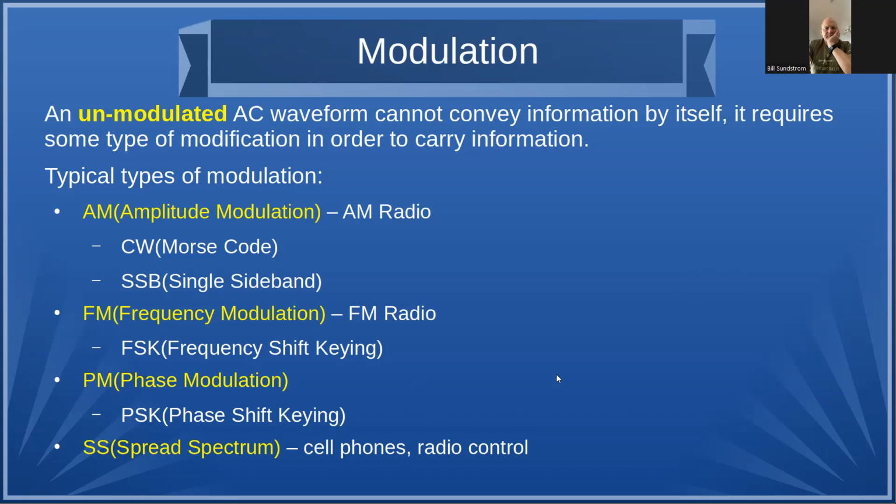Today, most of the phase modulation is in what we call phase shift keying for a lot of the digital modes. There's one called PSK31, which uses phase modulation. Very narrow bandwidth. It's 31 hertz. It's even better than CW.